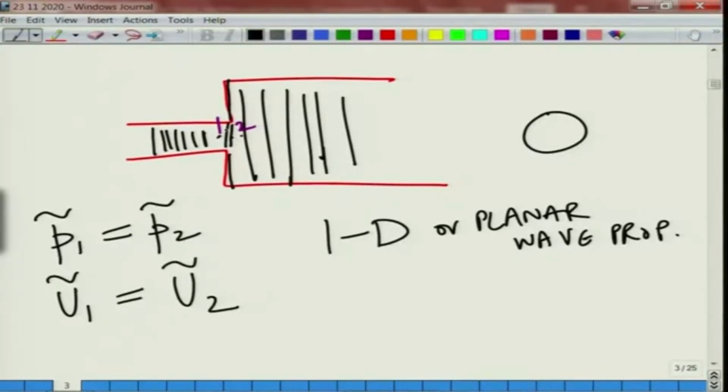Obviously, you are considering one section that forms one end of the tube, that is a smaller tube, and the other end a part of the chamber. So, of course, they are referring to the same points. The acoustic particle velocities have to be constant, that is u1 right here in the direction like this. They have to be the same because you are referring to the same point.